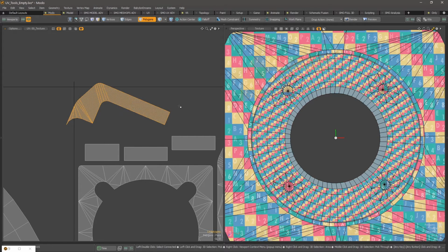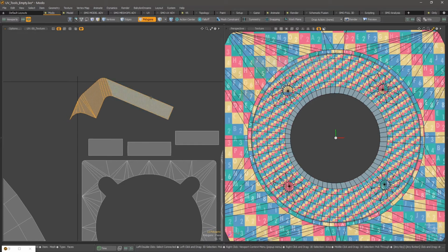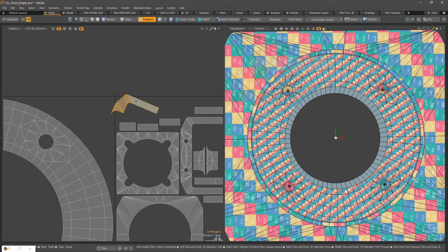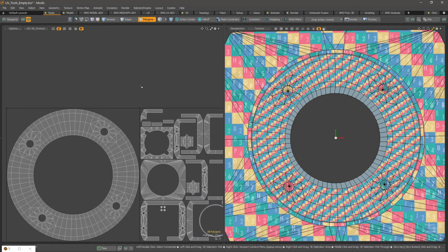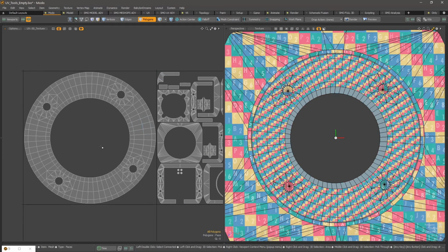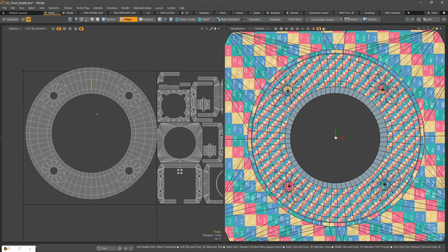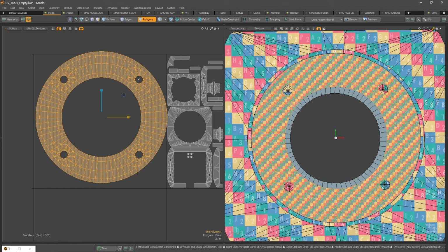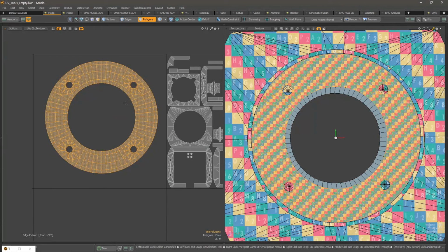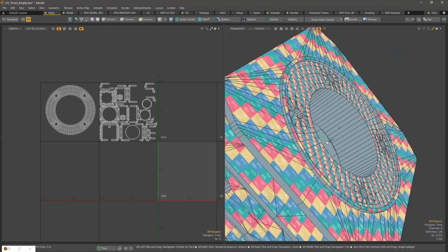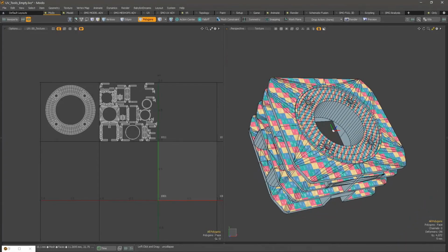So it constrains it horizontally to take the less space on the UVs, but you see that it automatically switch between the edge mode and the polygon mode if needed, because that's two different commands in Modo. So I will check this one and press the Shift Q and make this vertically. So now we have this correctly positioned, and we are done with this one. So this is one part of the work.